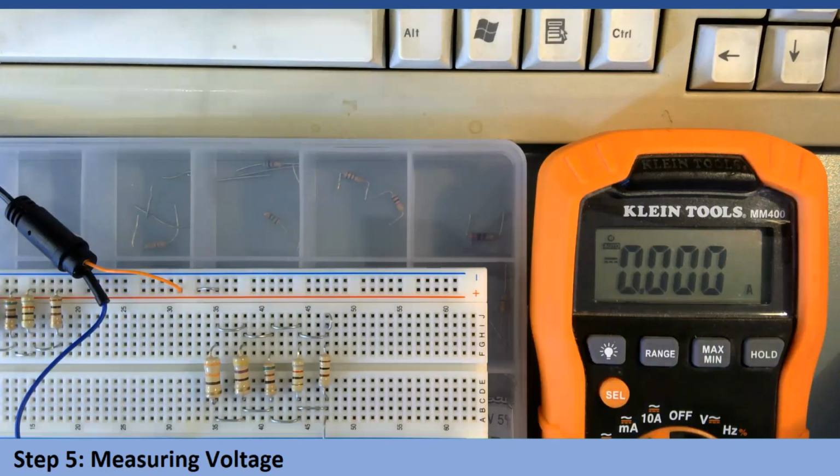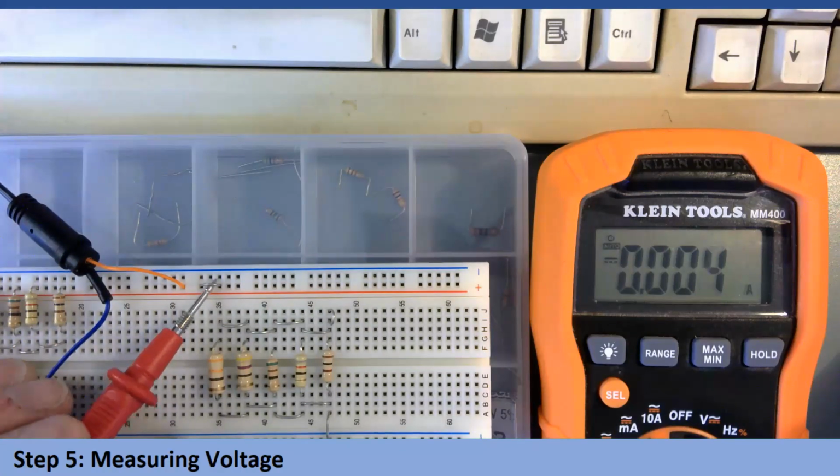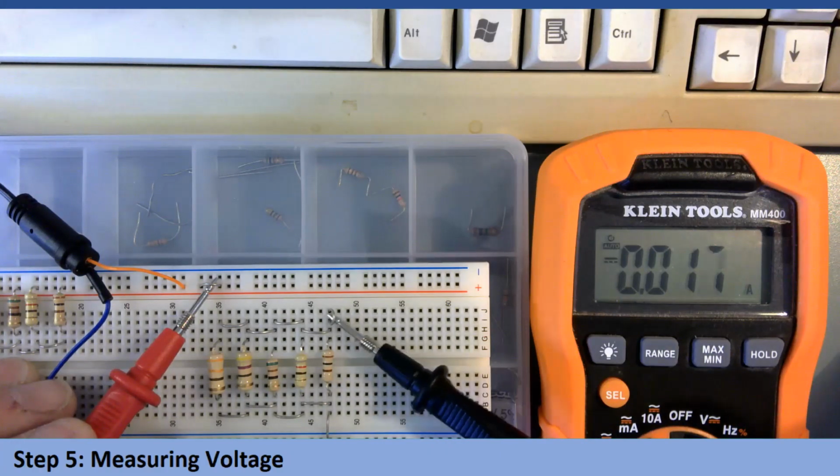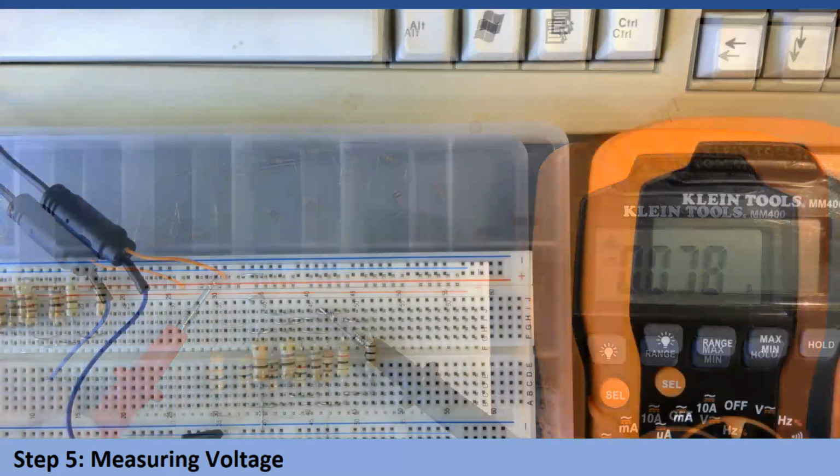So we want to again watch polarity. I've got two hoops that allow me to insert the meter. So I want this to be on the most positive side and my black to be on the most negative side. So I have another loop here. And it says I'm drawing 0.78 amps, otherwise 78 milliamps.